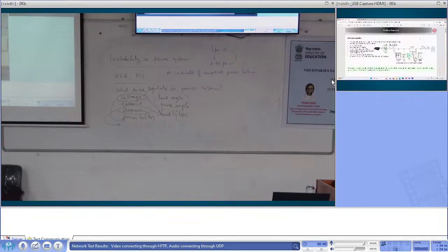Anyway, so it's very normal, by the way. In all, आप यहाँ लगाकर measure कर लें, you will never measure 50, because जो बड़ा generator होता है, which is power station, which is 3000 megawatts or plus there, they pull everybody. जैसे ये जनरेटर है that is dumping energy on this big guy, वो उसको तो कोई अंतर नहीं पड़ेगा, that will take it, and this guy will slow down on its own and lock in with the big generator. So normally frequency is not 50, it is 50, बदलती रहती है, and they have got an integral error which they put to 0.